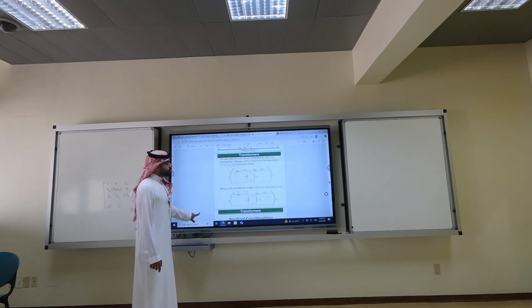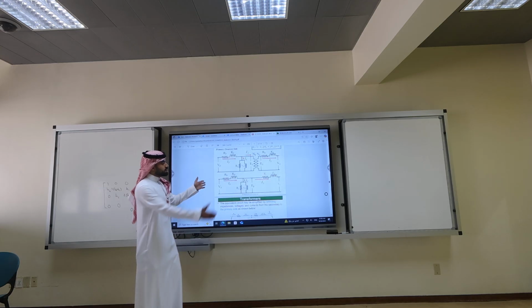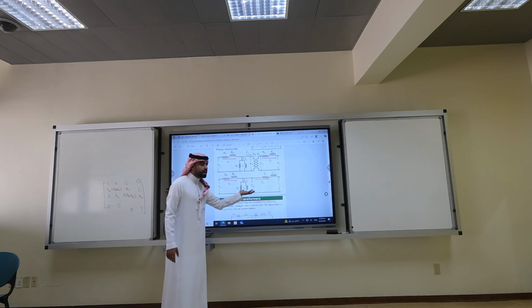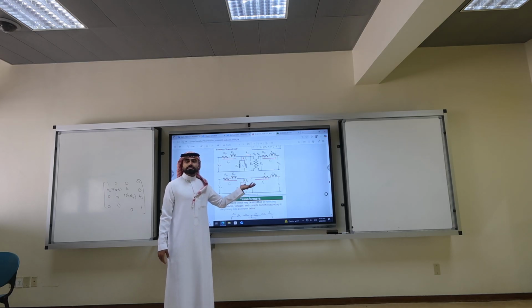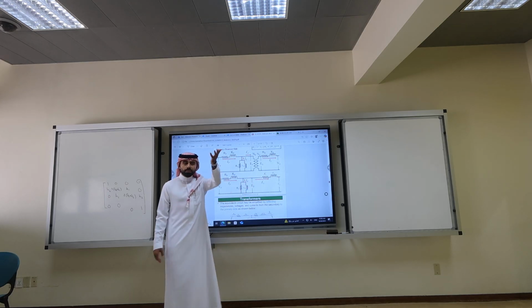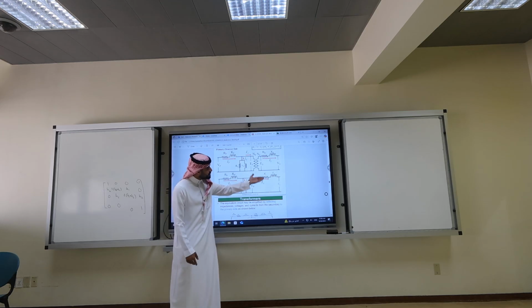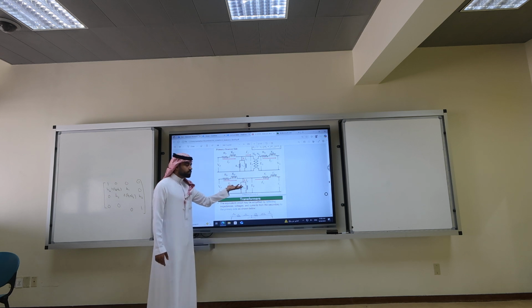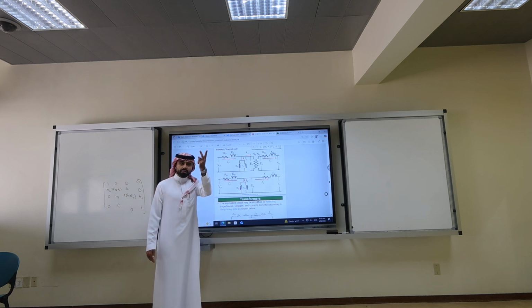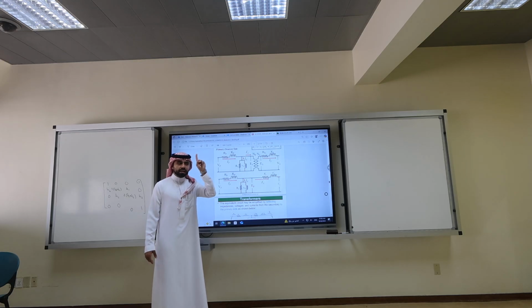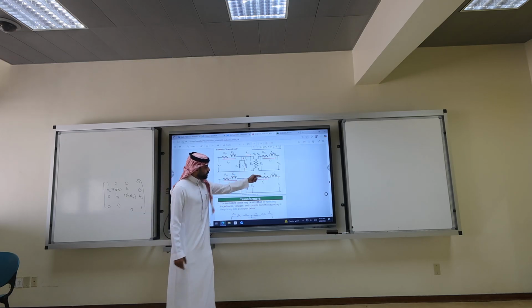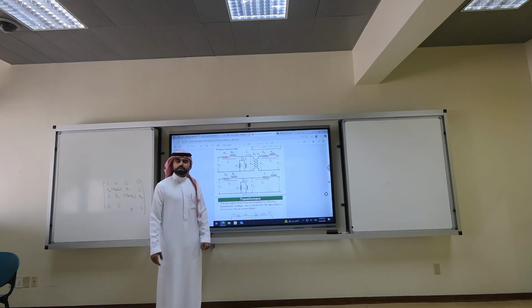So remember circuit 1? This is the original circuit. Was this referred to primary or referred to secondary? To primary. Referred to primary. Why? Because I see RS prime, XS prime, VS prime. What did I tell you about this circuit? We have to do 2 KVL and 1 KCL: KVL 1, KCL, KVL 2.